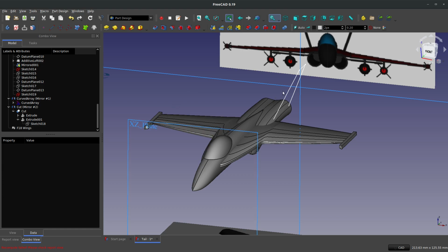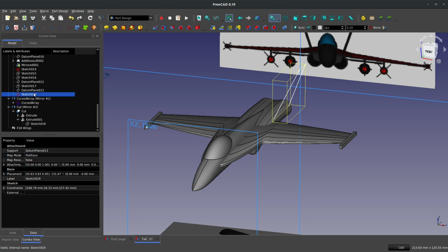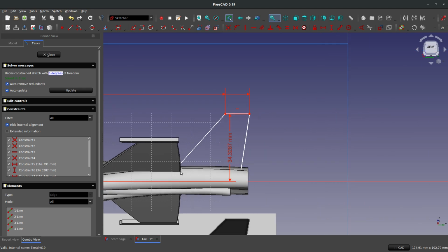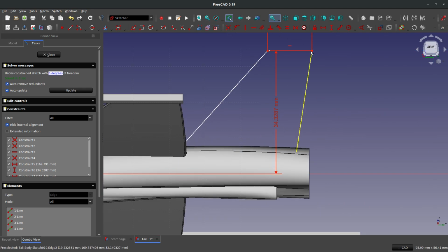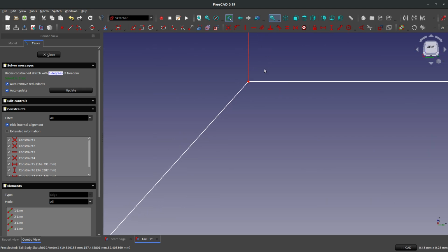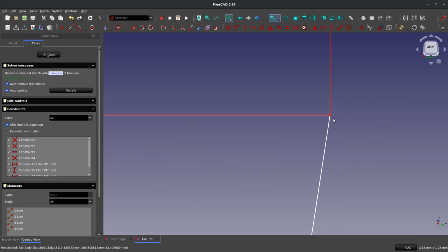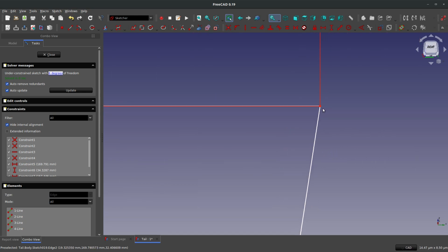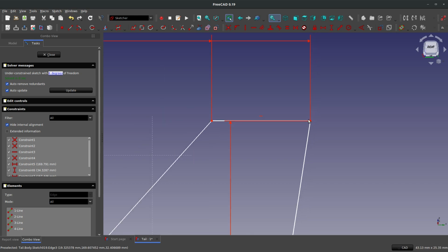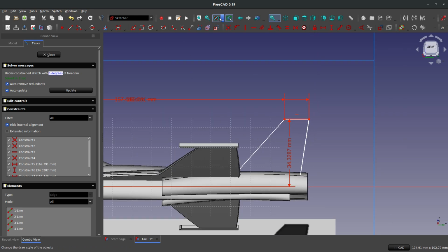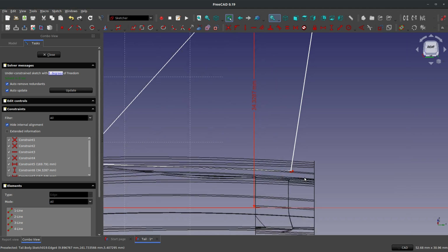Oh, and I've got the old failed to validate broken face error. So let's take a closer look at what's going on. This is our sketch 19 right here. I'm going to edit my sketch. Now the failed to validate broken face pretty much always comes from lines not connecting. And these, if I zoom way in, appear to be connected. So if I come over here, I'm seeing a good connection even when I zoom way in. I'm going to switch back to my wireframe view.